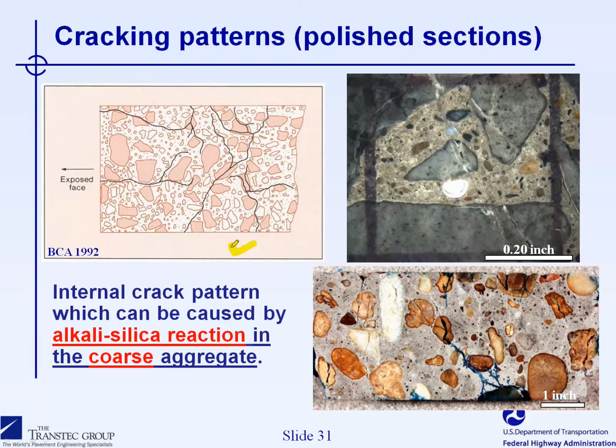These sketches of patterns of cracking have been proposed by the British Cement Association Diagnosis of ASR Handbook back in 1992. And in that document, you can see a number of those sketches that are presenting different types of deterioration in concrete, not only ASR, but also freezing and thawing, delayed ettringite formation, and other mechanisms.